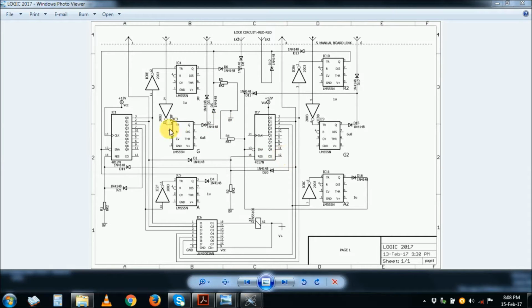As you can see, we have here the usual 4017, the Johnson counter, and then we have our lovely 555 timer circuit. For each side we have 3 timers, 1, 2, 3, and then the other side the same, plus or minus. You can see that it's a repeated circuit. This one, the 4017 counter, and then the 3 timer circuits. So this is our main control.